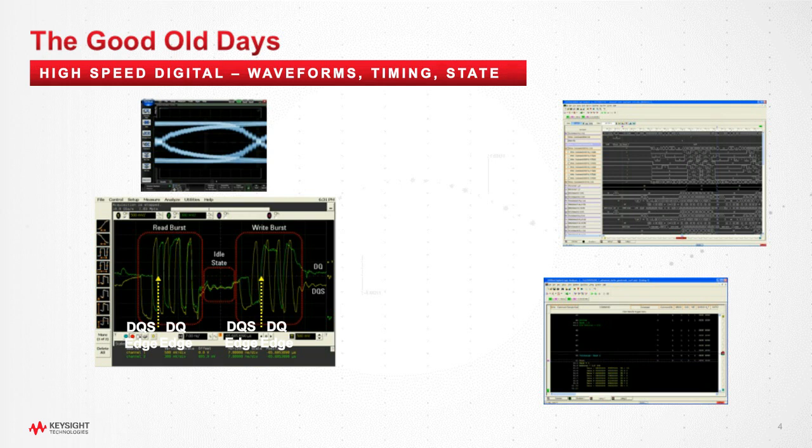So in addition to oscilloscopes, logic analyzers were really very important tools for everything up through DDR3, and they're still used up to DDR4. But when you're dealing with high-speed digital, timing diagrams are really the way you think. And so timing analysis, and then one step up to the protocol level to state analysis. This is the domain that we've all been living in for quite some time, and it's very comfortable.